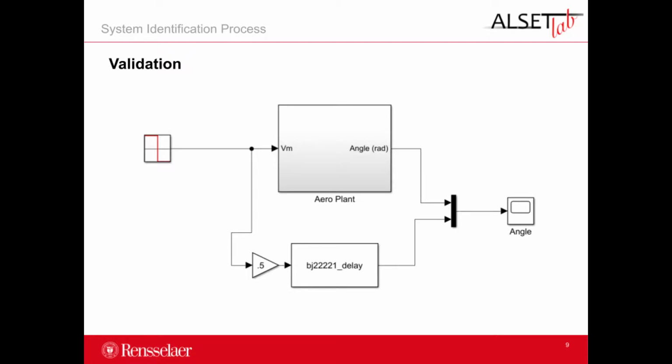If the model is determined to be adequate for its application, then the system identification process is complete, and the selected model can be used for simulation or other applications. Otherwise, the procedure should be re-evaluated for potential weak points that may have led to an inaccurate model, such as poor input signal design, an incorrect sample time, or poor model structure selection.